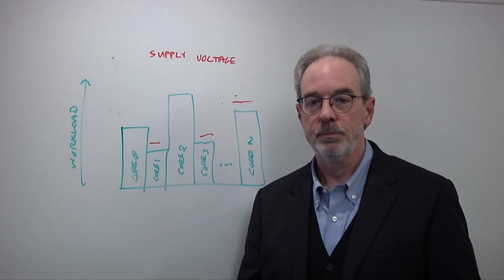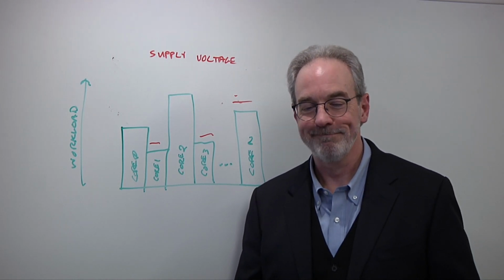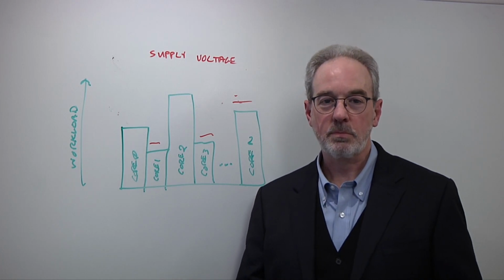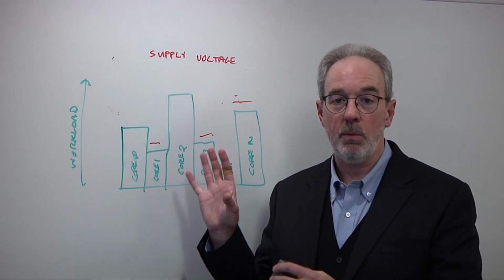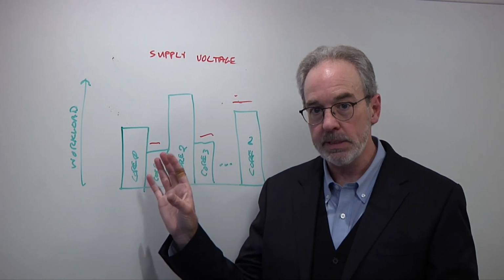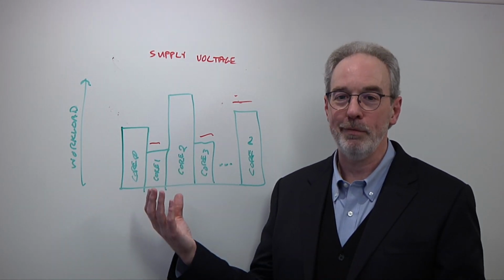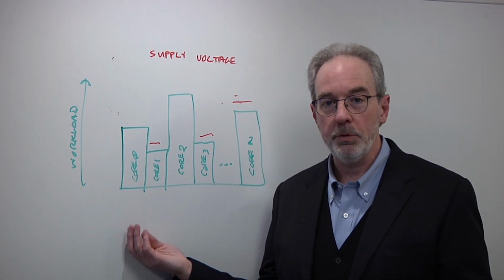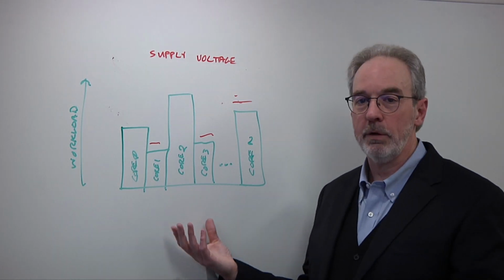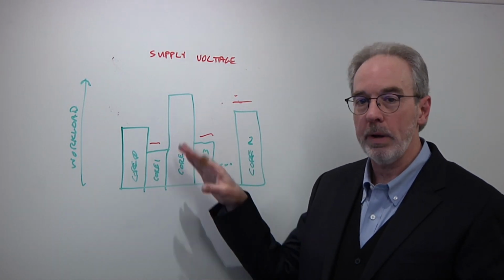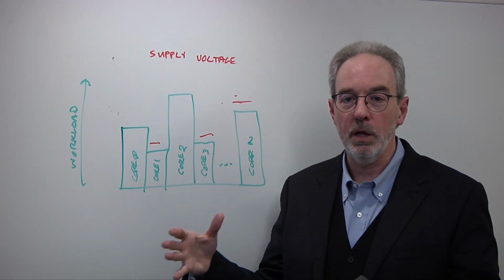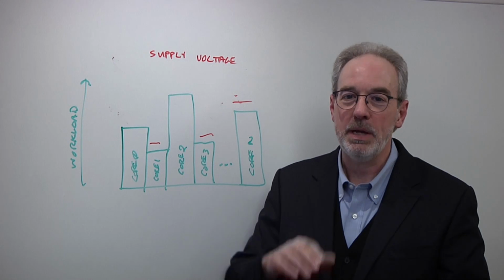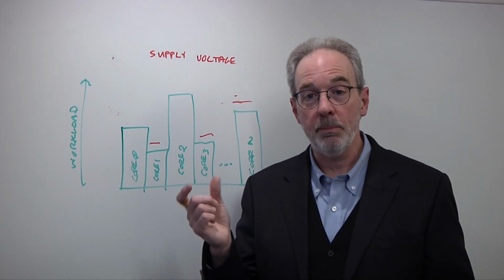This also allows you to do things like thermal management too, right? Because now you may have one core that's running hot. Okay, we need to move this over and distribute some of the load. That's a great point. I've been talking here about things that are entirely workload based, and certainly under software control you can drive this, but that doesn't have to be the only factor. And in fact, in the real world, they're often not. Thermal demands, system demands, chiplet constraint interfaces, all those will drive where and how you manipulate the voltage, spread the load. And in fact, in the 3D world, you may have devices that are on top of each other, so you have to be spatially aware as well as temporally aware.